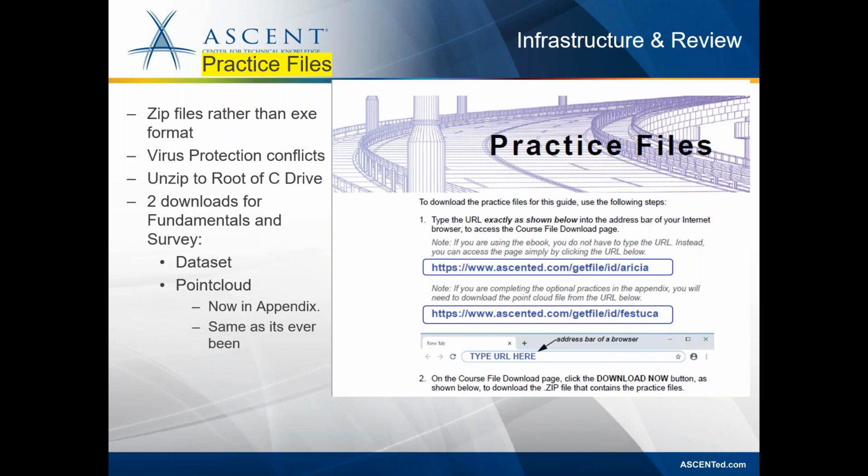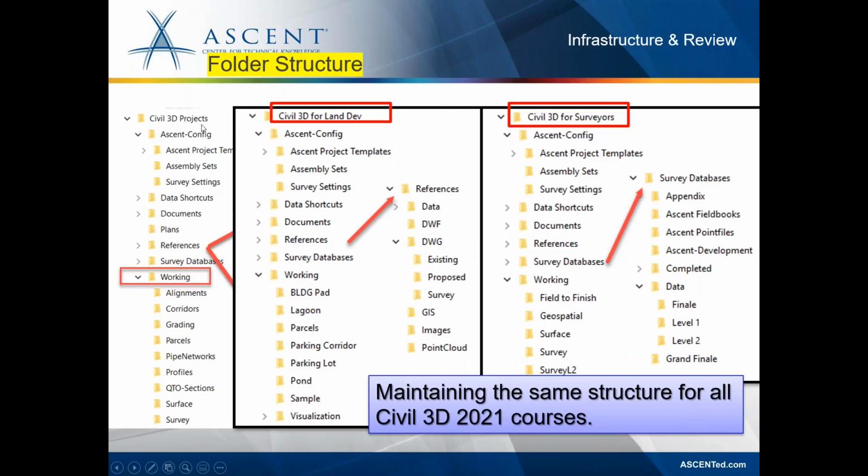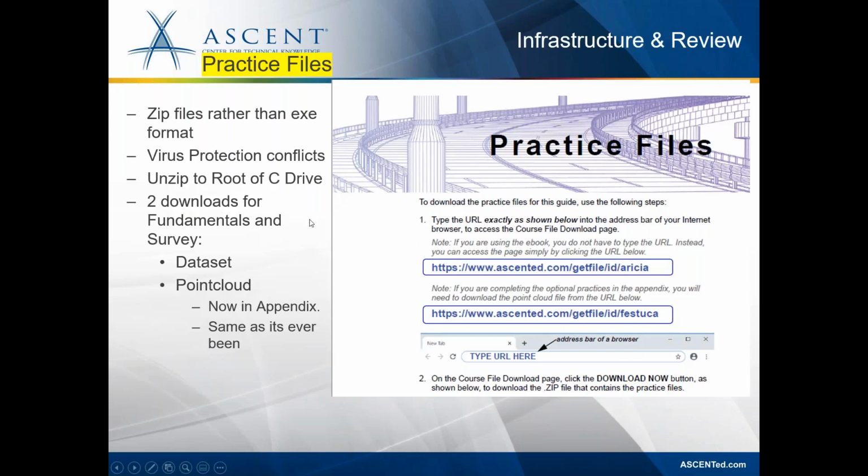So we just simplified the whole thing and made them zip files that you can download. When you unzip these files, make sure that they get unzipped directly to the C drive, and then they will go into these folders. They will automatically create the folder structures that we just looked at: Civil 3D projects, land developers, and surveyors.